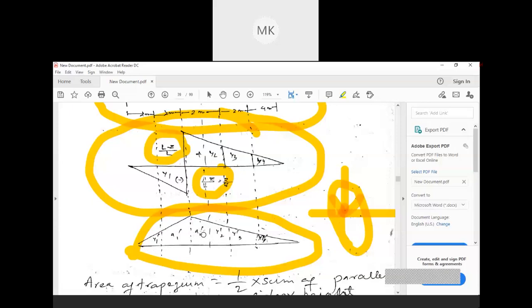Just write the values here, and below this figure and this figure, you simply write this is ILD for FC, or this is ILD for MC. Means maximum shear force at the point C and maximum bending moment at that point C. Okay, this is a very simple thing. Very simple. Just you need to remember this formula